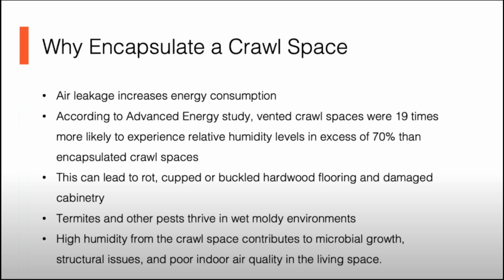One big reason is energy consumption. When it's hot outside and that air is coming in below the home, you're going to be heating up that space. In the colder times of the year, when you have a crawlspace that's ventilated to the outside, the insulation underneath the subfloor area isn't enough. The reality is, we're still bringing a lot of cold air into the house. This is another reason why energy consumption is a big reason people encapsulate crawlspaces.